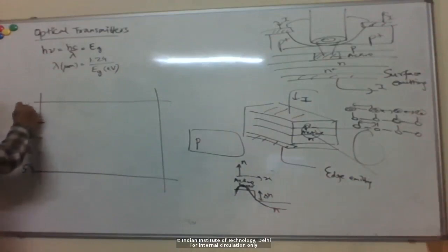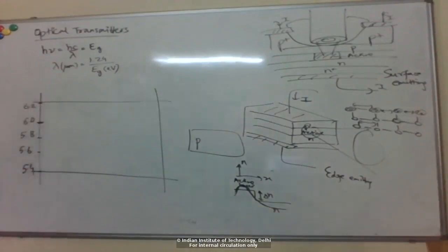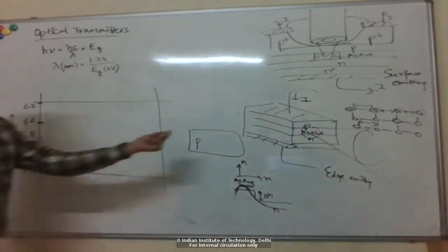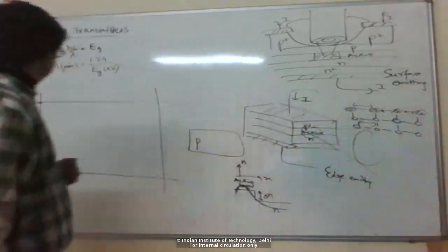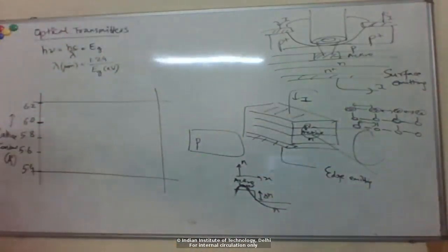using some combinations of these 3-5 materials. Here on the y-axis is lattice constant in angstrom, or 10 to the minus 10 meter, right? That's the typical interatomic spacing scale. If you take silicon, for example, it's I think 5 point something angstrom. So for most solid state materials, that's the range of the interatomic spacing.